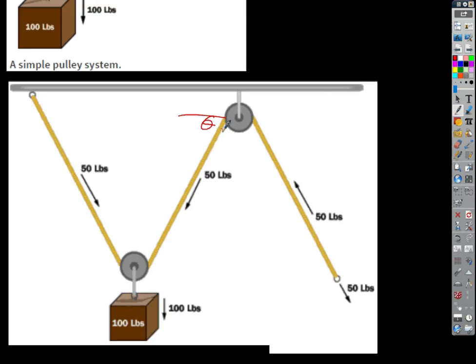So to make this better, what would we do? Move the pulleys closer to each other, so they hang more vertically, right? Yep. If you moved it more than right above it, well, that wouldn't be good. Then you'd still be changing the angles. You'd want to have those lines hanging vertically if you could, as close to vertical as you can. You want the lines parallel? Yep.